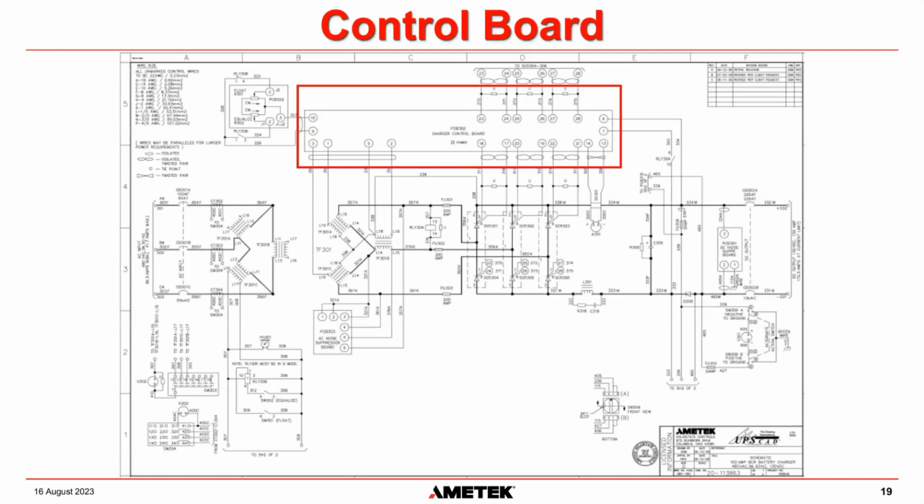So what the control board is doing is it's sending a signal on all of these outputs here. Okay, so I call them channels. So there are 6 channels for the 6 SCRs, and they go down to the gate signal of each SCR. You can see there's a gate signal there, and you can see the physical that there is the gate signal there going up to the control board. So for the SCRs to turn on, they have to receive a signal from the control board.